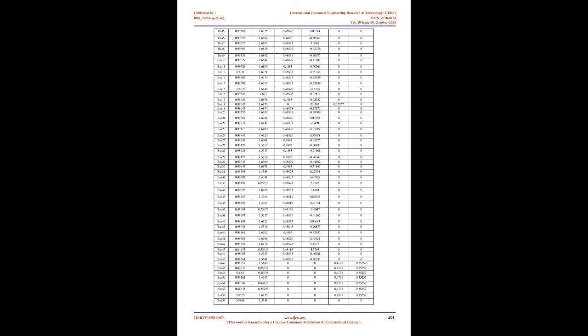When a three-phase fault occurred at generator bus 2, the continuation power flow result, power voltage (P-V) graph and voltage profiles are shown in Table 4 and Figure 10 respectively. The maximum loading point, collapse point, increases from 1.1753 pu, 352.59 MW, to 1.2166 pu, 364.98 MW, indicating an improvement in the system voltage stability index/margin.